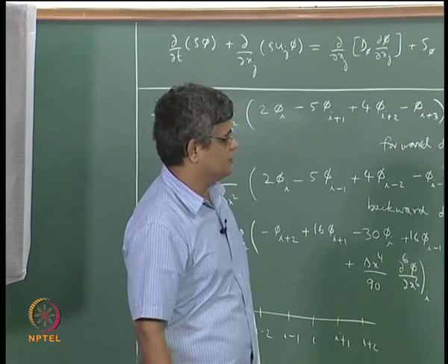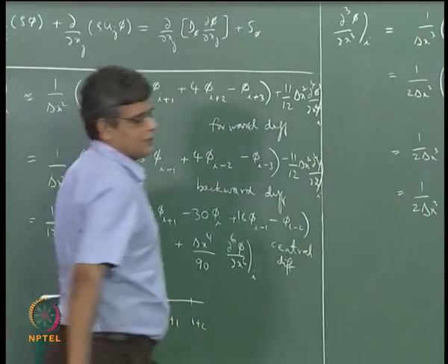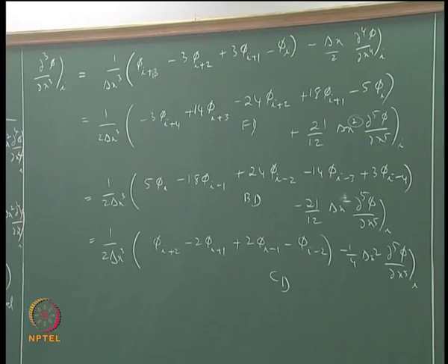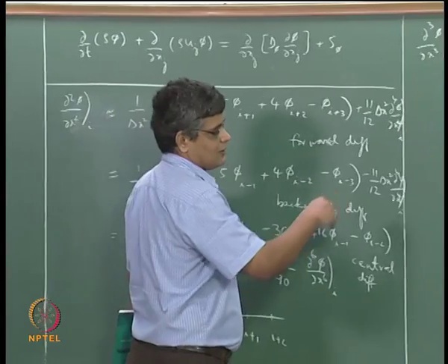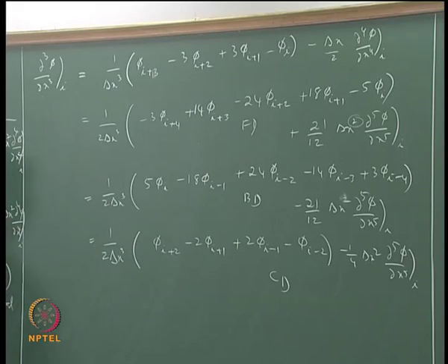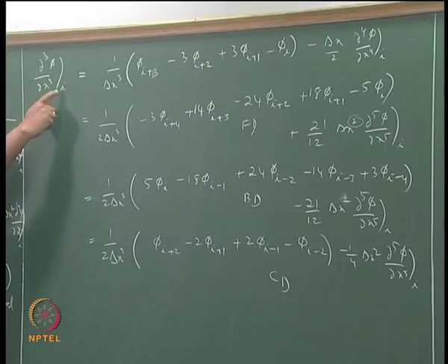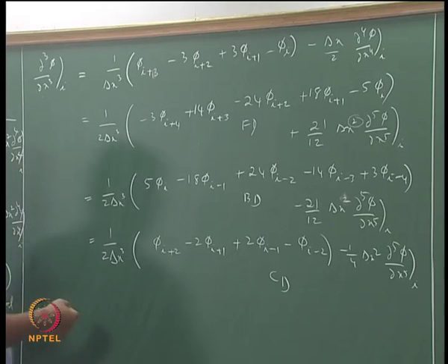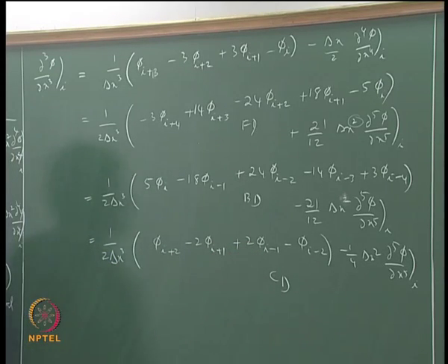Okay, so this enables us to take any derivative and then write a corresponding finite difference approximation, and thereby taking each derivative that appears in the governing equation and substituting it with the corresponding expression, we will be able to convert a given partial differential equation at a particular point ij or ijk into a corresponding finite difference approximation involving the values of the particular variable at the grid nodes at which we want to find out the values.